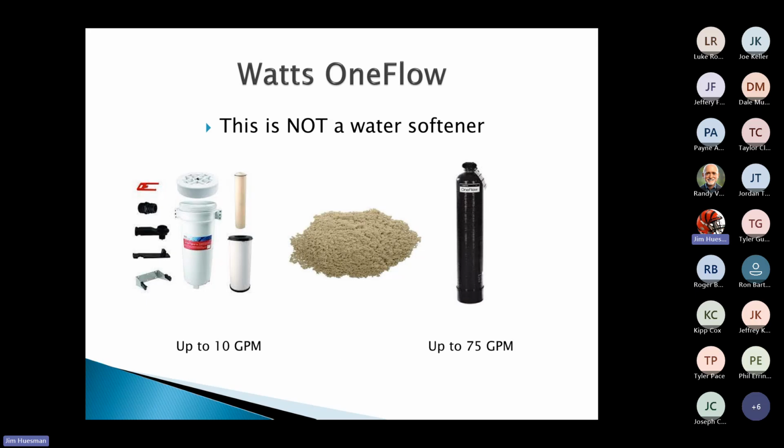And the great thing about it is this tank is not filled to the top. It's only about 25% full. So to change that media, we have 2 unions, unscrew the head, and the whole thing pulls out. I normally would just dump it into a 5-gallon bucket and then toss it. It's not biohazardous, so you can just throw it right away.